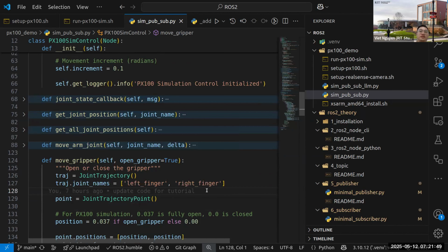Sometimes when you want to enable the control type or control mode of the robots, for example, you have to use the service of the robots. So for example, controlling by velocity or controlling by 3D coordinates, Cartesian coordinates, for example. If you want to control the robot by specifying the 3D coordinates in the 3D world, you have to change the mode to that. And the way we do it is we use the service, right? That is also one application of using the service.